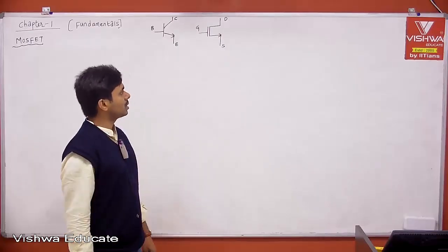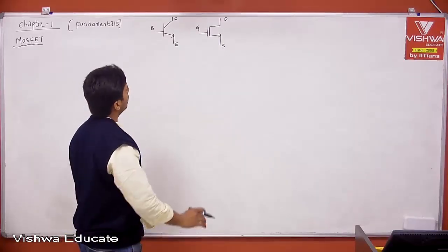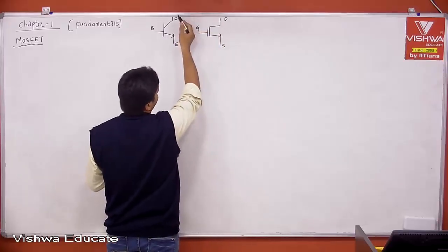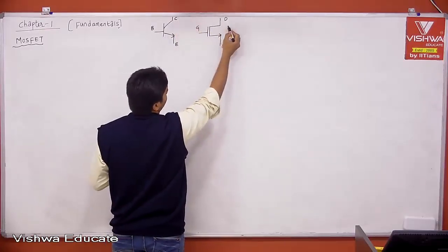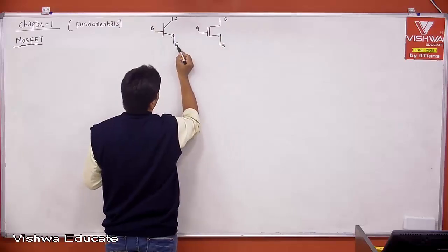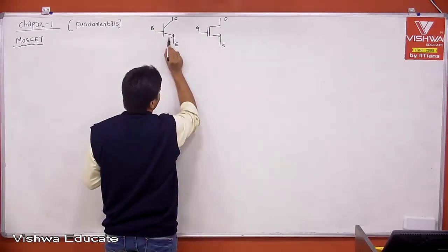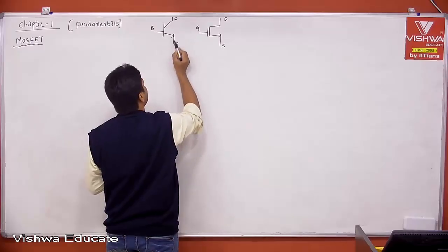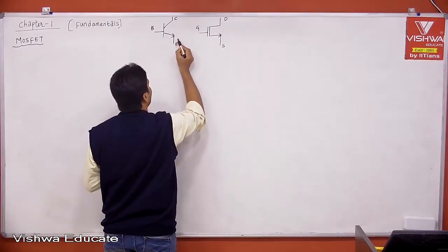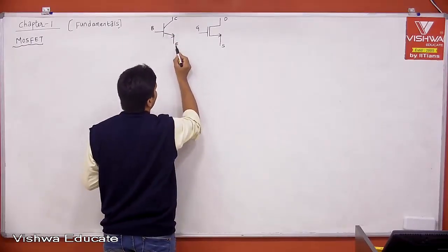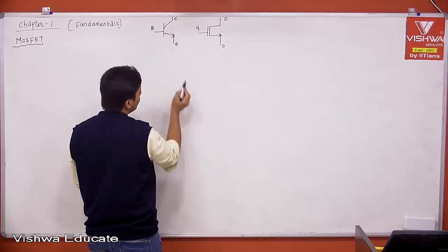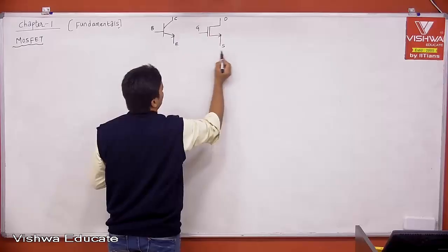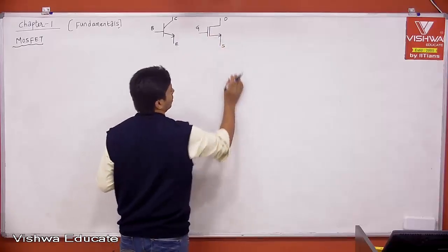These are all variable voltages, therefore we need to show. When I say collector, this is what is drain. As I told you, collecting the carriers, draining of the carriers. Emitter, emitting the carriers, but the direction of the current is opposite. Electrons are flowing like this, emitting the carriers, then opposite to electron flow is your current flow. But I am speaking with respect to carriers flow, or electrons flow. Therefore, emitter is the one which is emitting the carriers, source is the one which is sourcing the carriers.